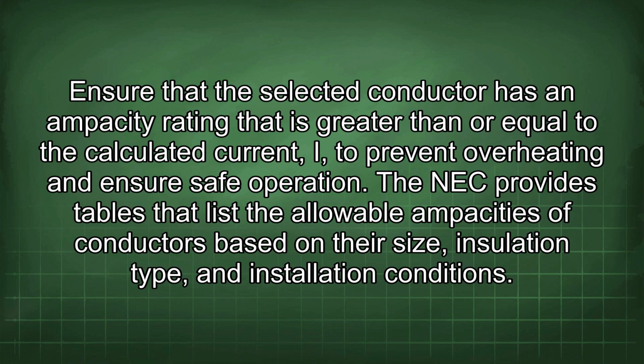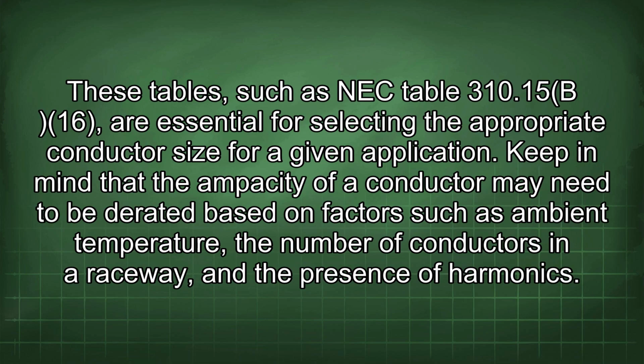The NEC provides tables that list the allowable ampacities of conductors based on their size, insulation type, and installation conditions. These tables, such as NEC Table 310.15(B)(16), are essential for selecting the appropriate conductor size for a given application.